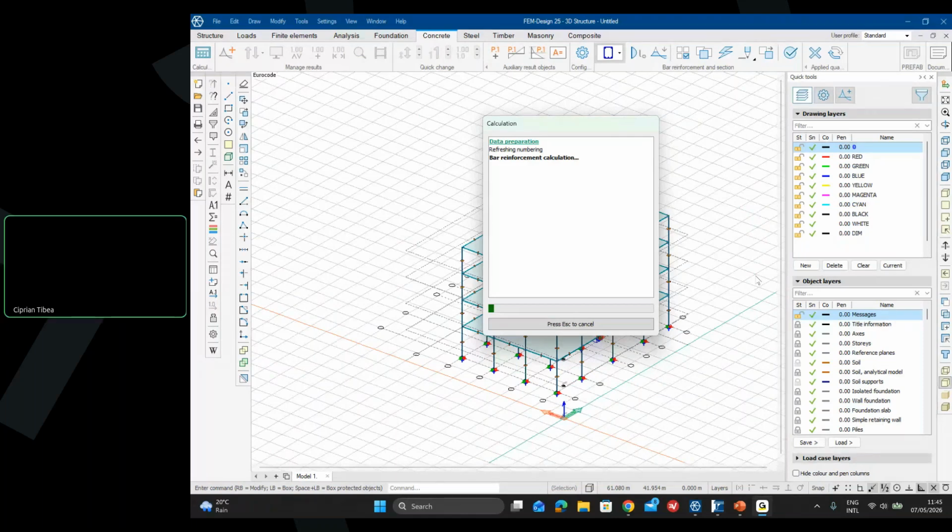You can just say a name, load combination number 1, and then the next column will be the safety factor, and the next one, you will select from a drop-down menu the load. Then you go on the safety factor column beneath it, and you select the next safety factor and the next load, and so on and so forth. So that's how you manually input your own combination.